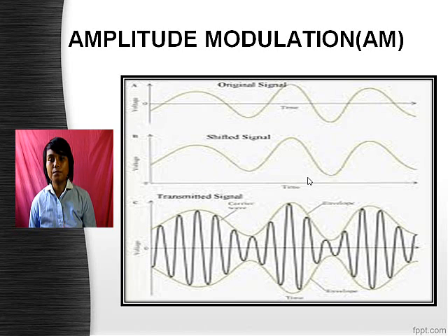The transmitted wave can be broken down into its components, and the information sent along with the wave is non-periodic, so a Fourier transform must be used. The collection of amplitudes for the different component frequencies is called a spectrum. This spectrum contains two groups of frequencies called lower and upper side bands. Here in the diagram, A is the original signal, B is the shifted signal, and C is the transmitted signal in which an envelope can be seen clearly.